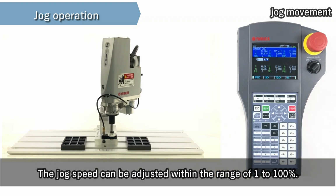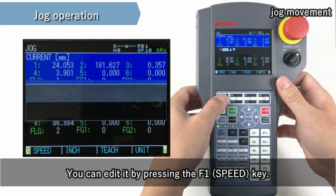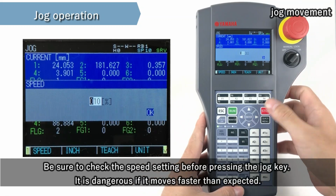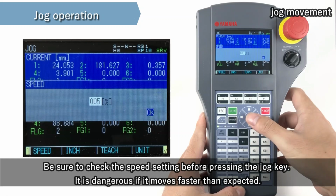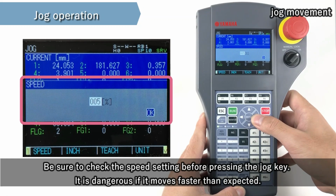The jog speed can be adjusted within the range of 1 to 100%. You can edit it by pressing the F1 key. Be sure to check the speed setting before pressing the jog key. It is dangerous if it moves faster than expected.